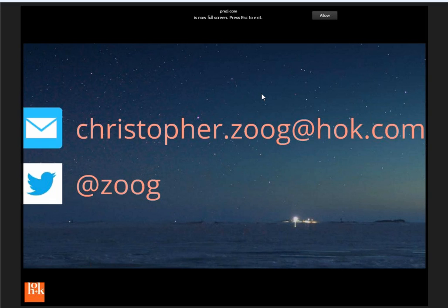I mean, I guess in theory you could, but I don't think Revit handles IFC import. I don't know. Mike Ortega from Cisco is sitting right here, he knows a lot about importing into Revit MEP. So do you believe there are tools out there that let us convert our files to an IFC file? The only one I know for sure is QuickPen. They have what do they call it? It's called Design Link or something like that. It's an add-on, I think, to their product.